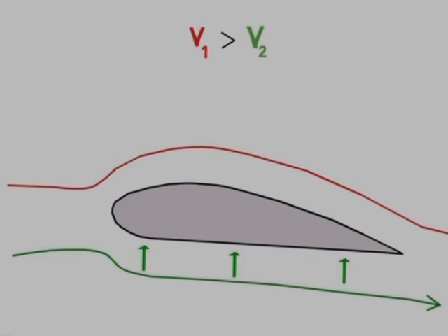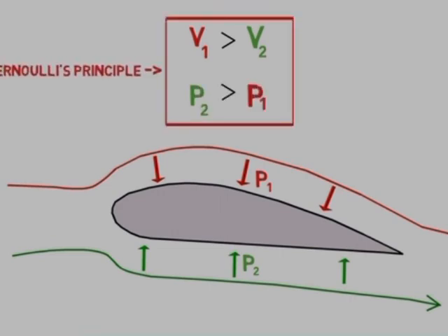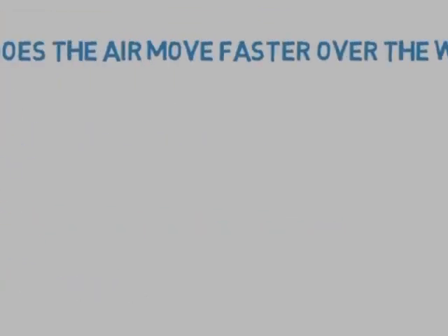If this condition happens, then there will not be any lift generated. So based on Bernoulli's principle, the air particles touch the leading edge of the wing and divide into two parts, one part flowing on the upper surface of the wing and one part flowing on the lower surface of the wing. Higher speed over the upper surface and lower speed under the lower surface should reach the trailing edge at the same time.